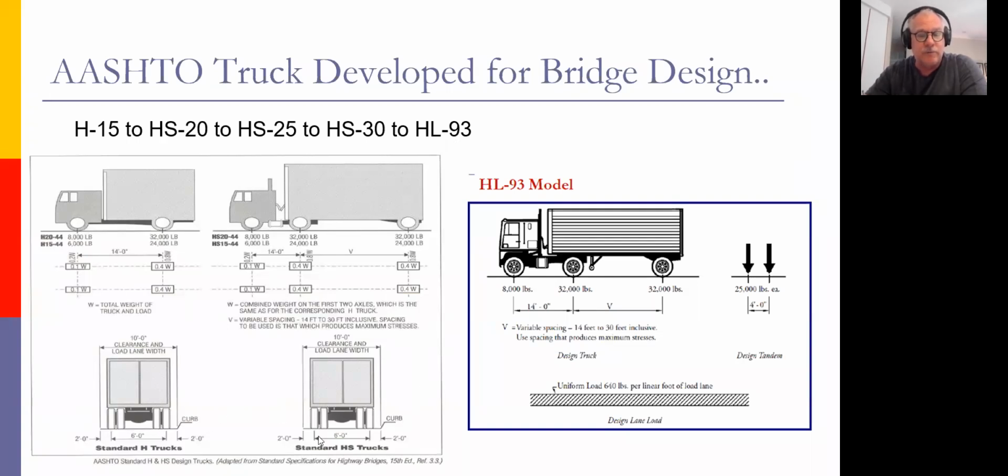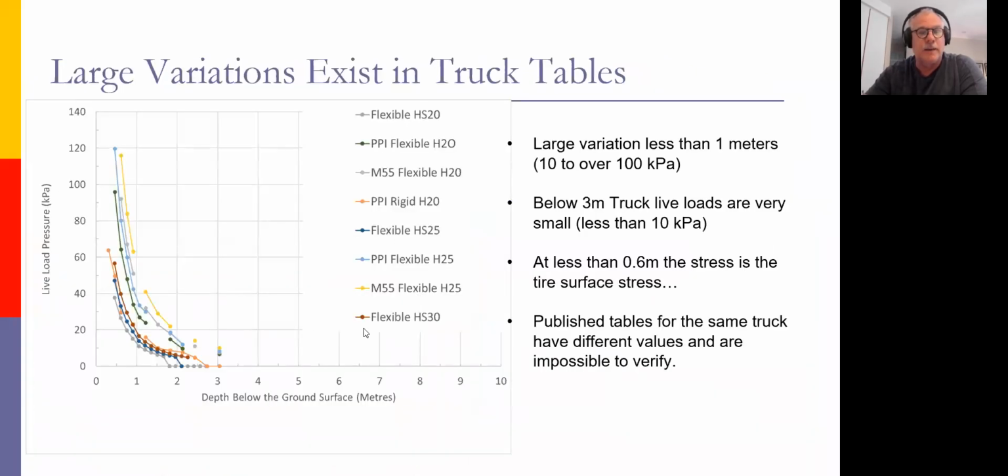So these trucks have a certain footprint, and we take the weight of that truck and distribute it according to different axle weights. For 40% of the total weight is on this axle, another 40% on this one, and then we do some calculations in order to be able to do that.